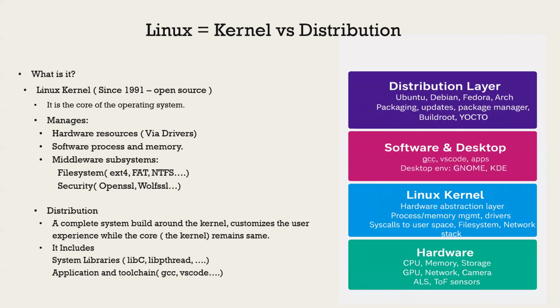This hardware abstraction layer provides you those features. So the application doesn't care about the hardware. It interacts directly with the hardware abstraction layer, and the hardware abstraction layer routes your data to the available port. So if you're connected to Wi-Fi, it will stream your data through Wi-Fi. If you're connected through Ethernet, it will stream your data over Ethernet. That management is done by the hardware abstraction layer.